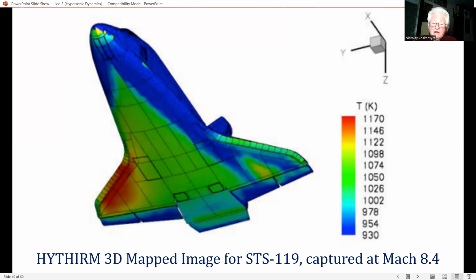Very recently, the NASA Ames Research Center developed a new aerodynamic prediction code labeled CBAERO, the configuration-based aerodynamic software package, much in the same spirit as the earlier HABP. This new code makes pressure predictions using the modified Newtonian, tangent wedge, and tangent cone methods discussed in today's lecture.